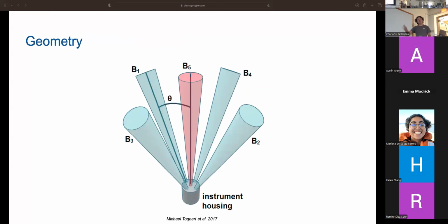This is a nice diagram view of what the instrument itself sees. If you didn't know, ADCPs actually don't make concurrent measurements of the same spot. These are divergent beams, meaning that at range, your actual uncertainty of your velocity measurements increases because you're no longer measuring anywhere near the same water mass or parcel of water. But the assumption that we generally use is that the statistics here are going to be pretty much the same as on the opposite beam. Well, actually, we assume this middle one.